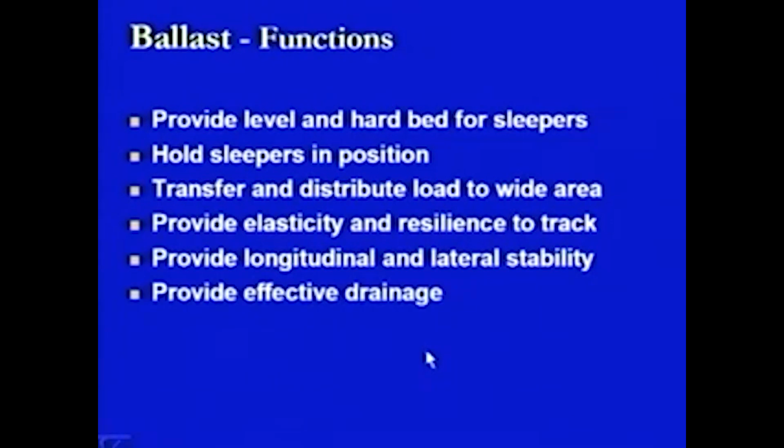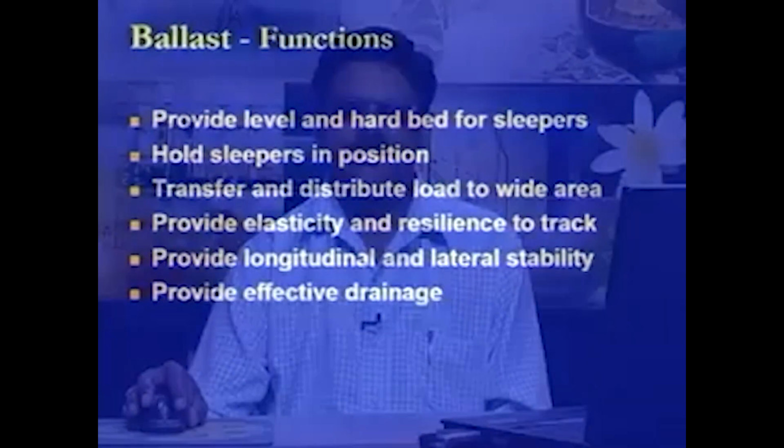Then it should provide effective drainage. If the drainage is not there, then the life of the material which is used in the ballast or the life of the sleepers is going to be affected. So, that is why effective drainage is required.